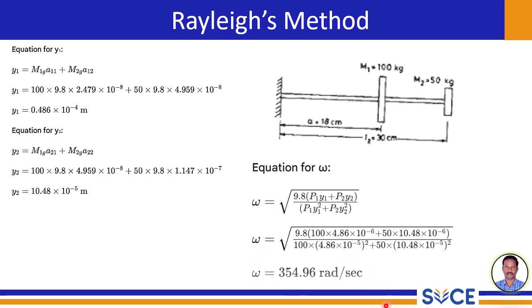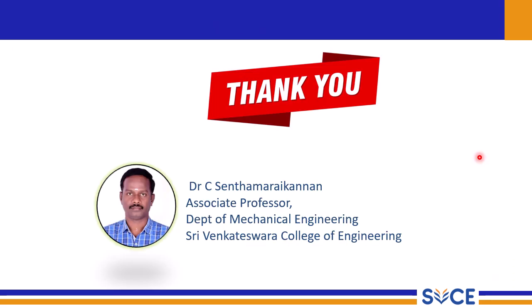This numerical result gives us a quantitative understanding of the system's natural frequency based on Rayleigh's method and the static deflection approximation. Rayleigh's method is an energy-based approximate technique used to estimate the fundamental natural frequency of a vibrating system by equating its maximum kinetic and potential energies.